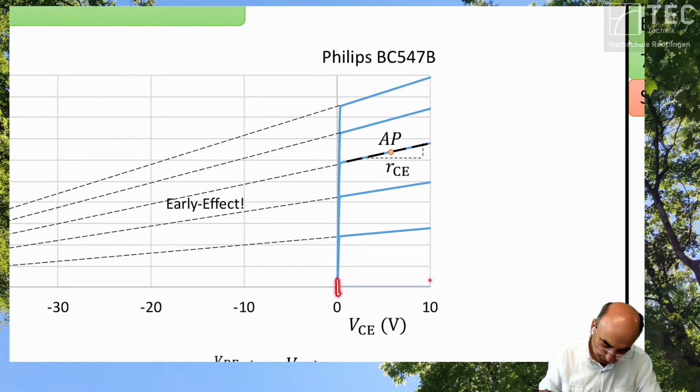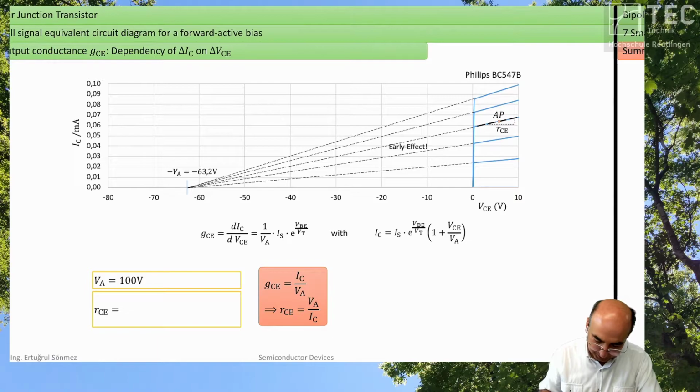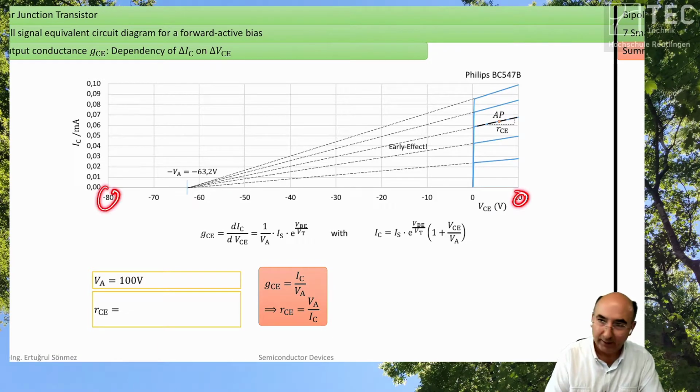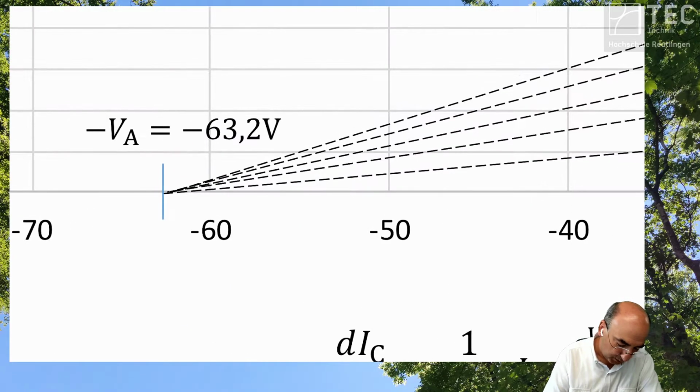So the usual output characteristics I have plotted in this scale using this bipolar transistor, which is a standard small signal transistor. And if you plot that device and use a large scale, then you see the virtual elongation, the interpolation of the slope, that all of them intersect at one point.